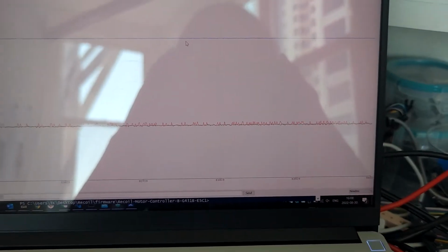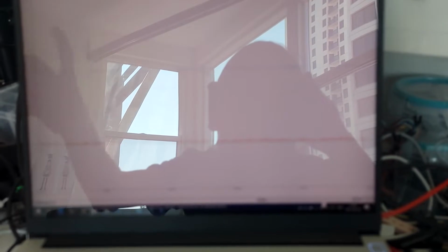So I tried the open loop, where I directly command the IQ and ID to the motor controller and let it spin. It spins perfectly fine, which means that at least the inverse Clark, inverse Park and SVPWM math is correct.